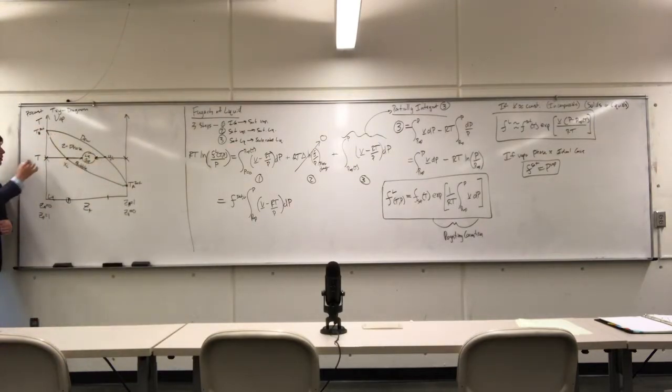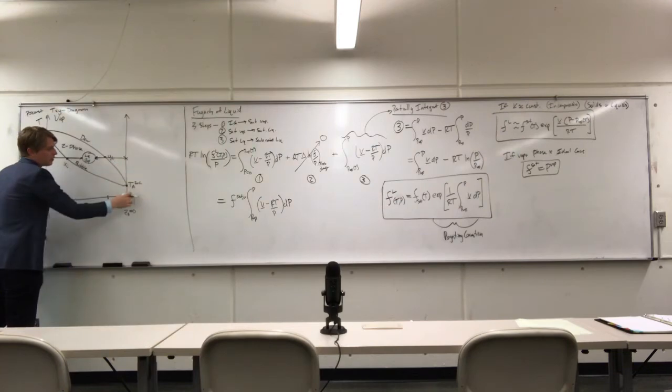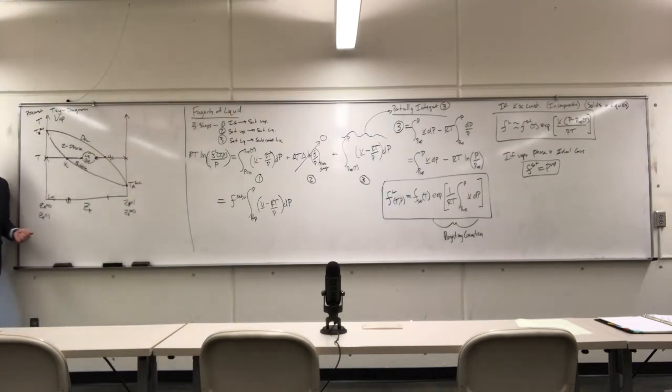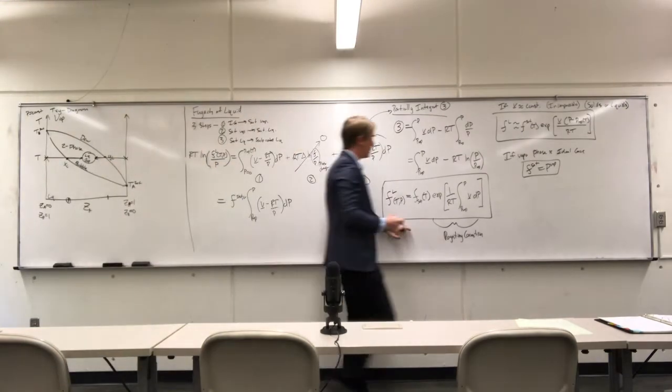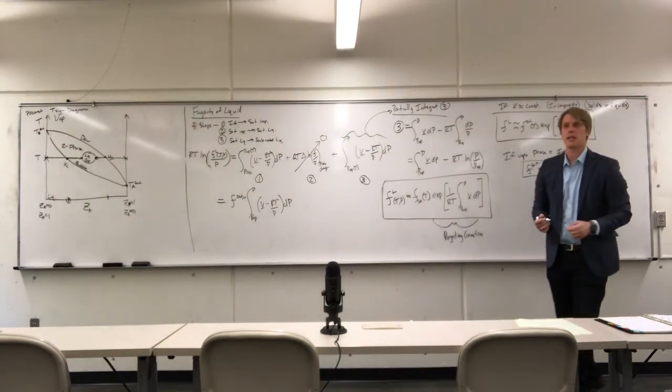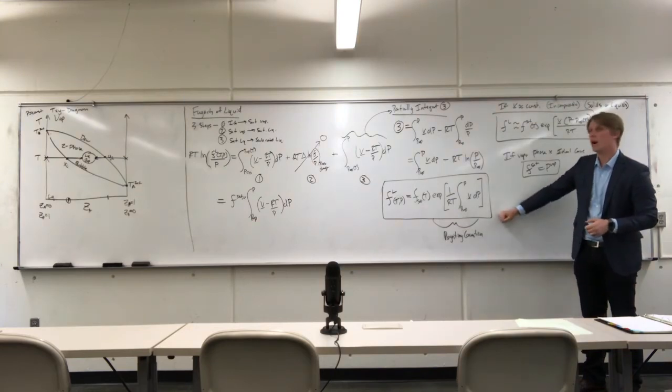Which means that I'm going to have to calculate the properties of a fluid that doesn't necessarily exist, right? Because I'm going to need to calculate the properties of vapor fluid B, even though it wants to be a liquid. I'm going to have to calculate the properties of liquid fluid A, even though it's going to be a vapor. And this is why it's important for us to keep track of all the different changes and properties that happen when we're looking at the fugacity at some sort of analytic pressure.